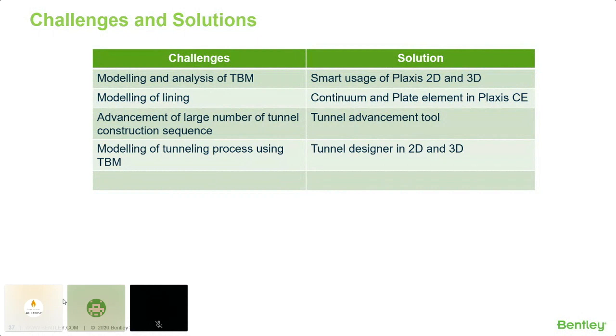By using the PLAXIS program smartly, you can model only those processes which are important. You don't have to model all the processes to get the correct results. So by modeling those processes correctly, and choosing a few excavation processes, you can model the complex TBM problem easily.